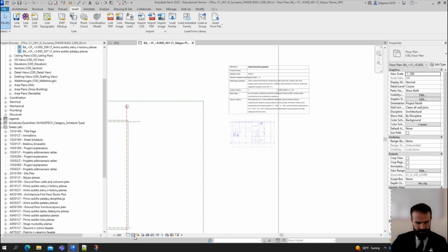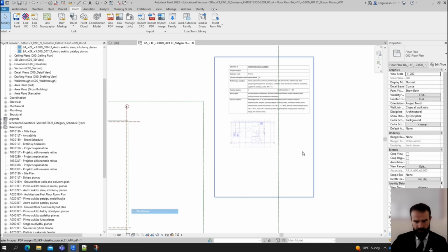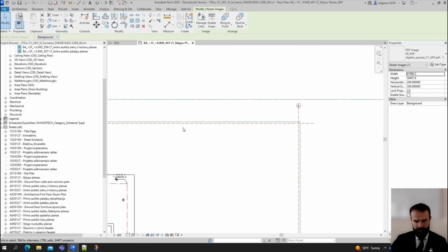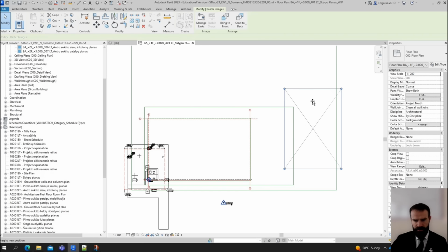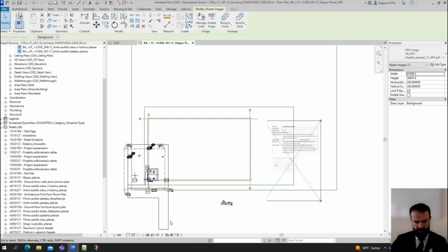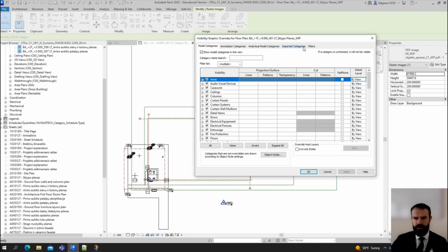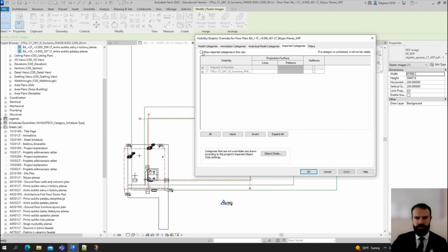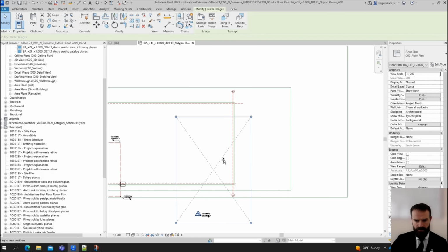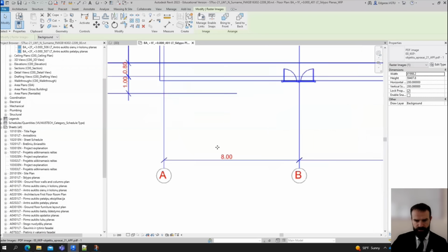So if I want to see it transparently, I click wireframe, so I can see through the drawing. And of course, I think my Forma and drawing is giving me additional problems, so I can turn off imported objects like Forma, and now my view is better.